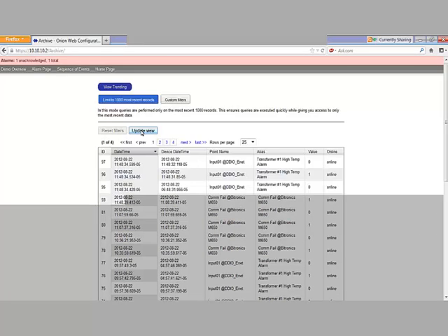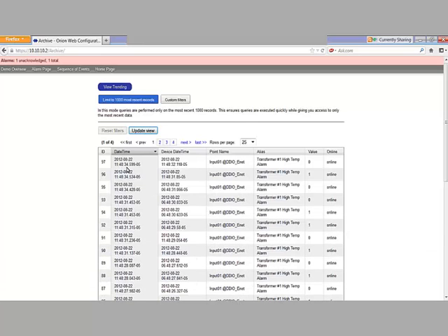There they are. You can see 11:48:34.599, and that's offset by 5 hours from UTC time. And you can see the toggling in the value column, 0, 1, etc. Again, this is a pre-formatted page that comes with the sequence of events and alarming module.